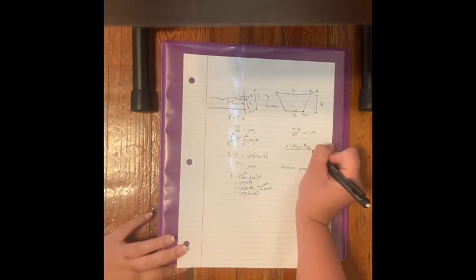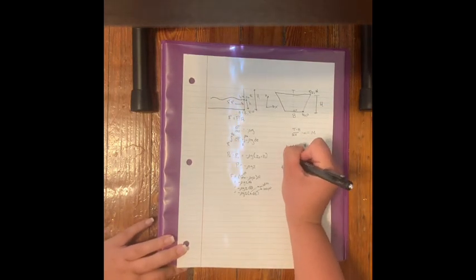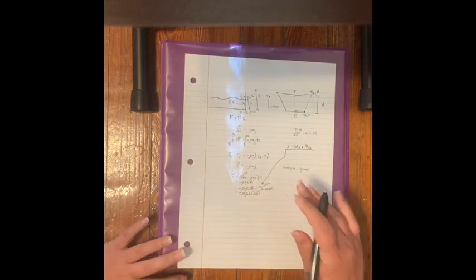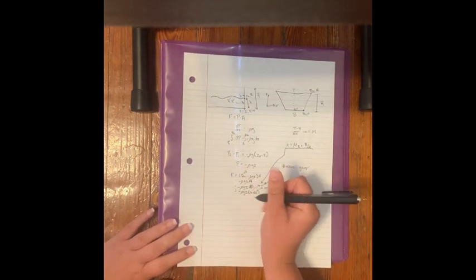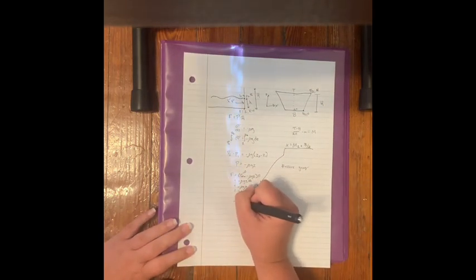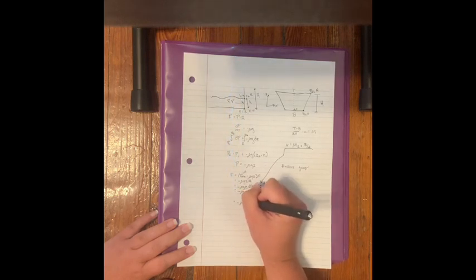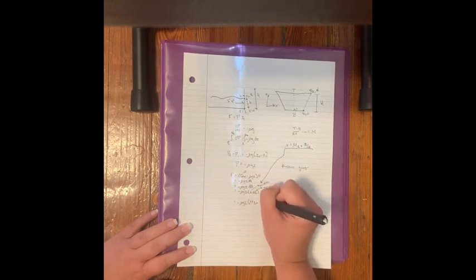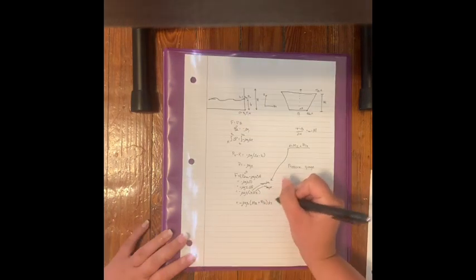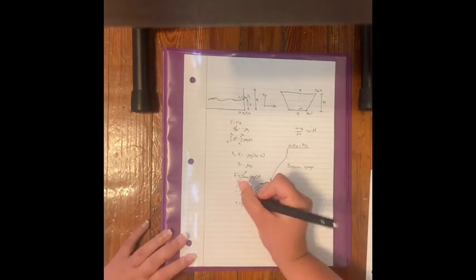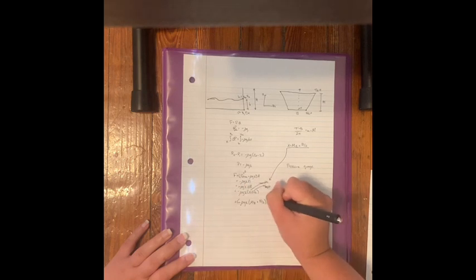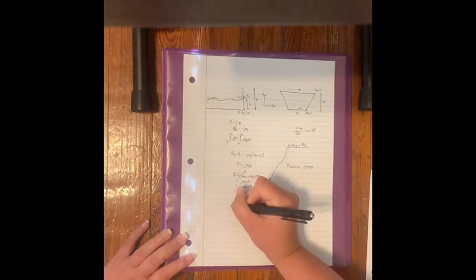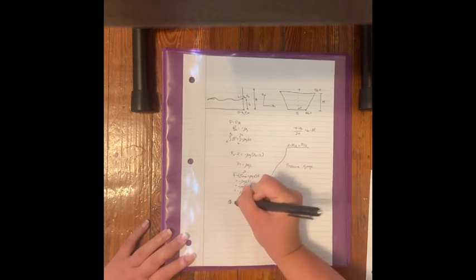So now we can plug in this expression to here for our width. And what we'll get is that it will be equal to the negative density times acceleration due to gravity times z times capital M z plus our bottom width over 2 dz. Because of how we defined our points here, we'll need to multiply this entire part by 2, which will now be equal to our change in force.